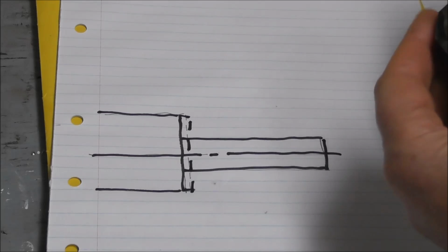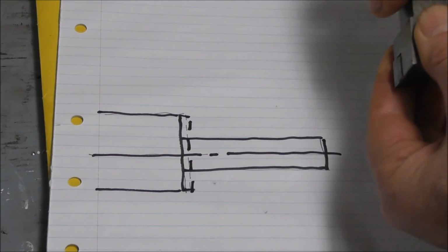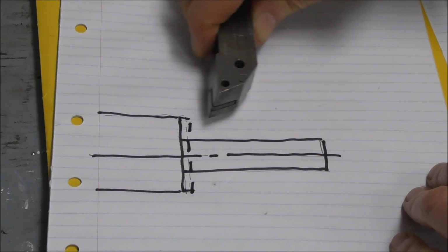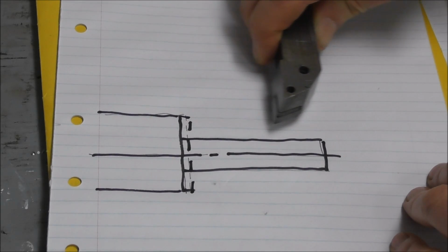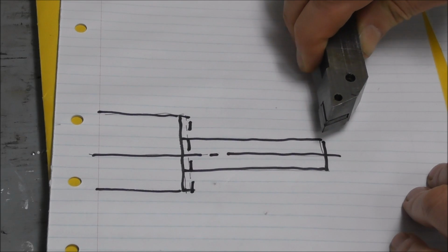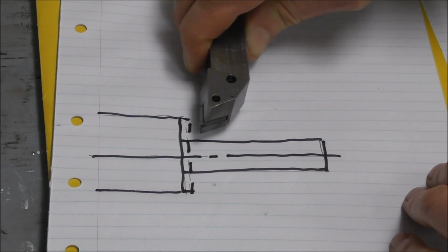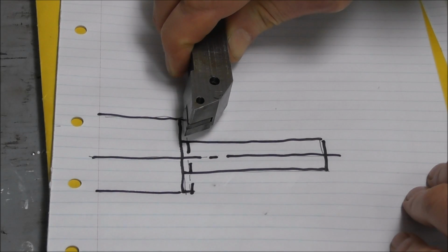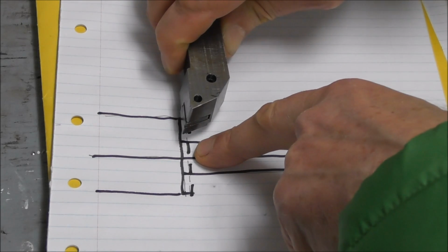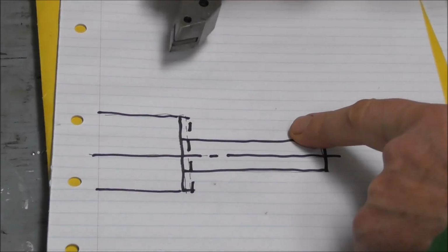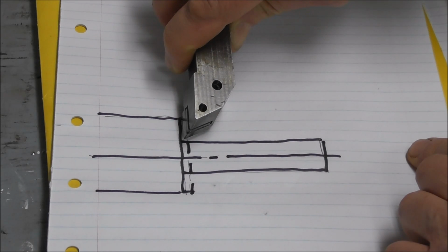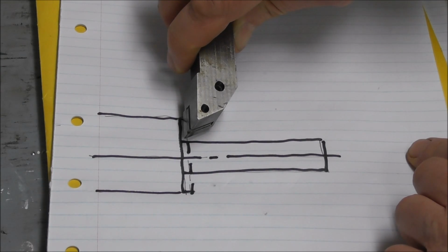So the way the conversational works, unless I'm doing something wrong, is that it takes the roughing cut to there, pass 1, pass 2, pass 3, however many there are, and on the finishing pass it goes the whole way, which would cause a huge cut right at the end of the depth of the finishing pass, and then comes back in like that. Now, I might be doing something wrong, or there might be a fault with the software.